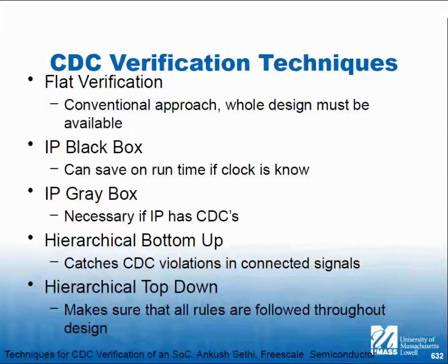So when you define that slightly different clock, make sure that the simulator isn't going to round it off to the same period as the other clock. You might even put some randomness in so you modulate the period a little bit. Bottom up, right? So you actually go down and look, or top down. So these are black box, gray box, white box.